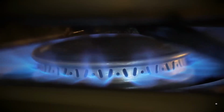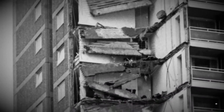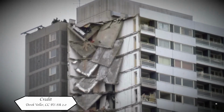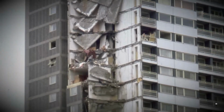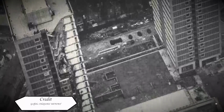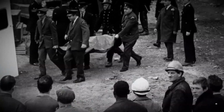A gas explosion happened on part of the 22nd story, and then the entire part of the block collapsed. The key reason for its collapse was that the building was constructed from blocks. Blocks were stacked on top of each other, so they were not connected with each other. After that, research on robustness and disproportionate collapse started around the world, which means that any frame in a structure has to be connected with other parts of the structure.